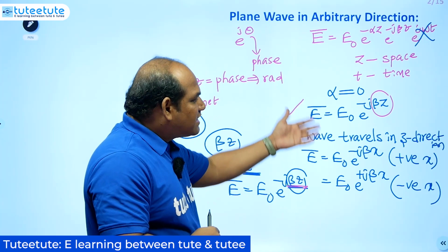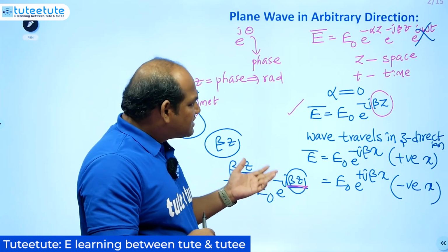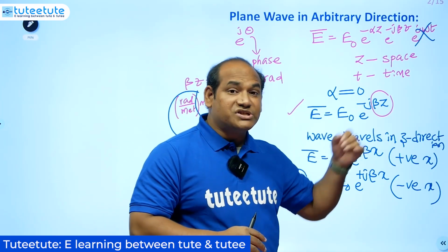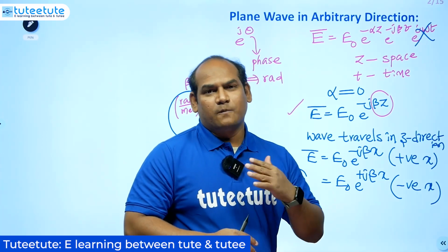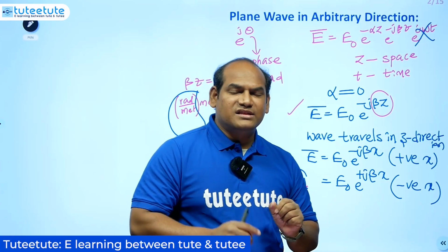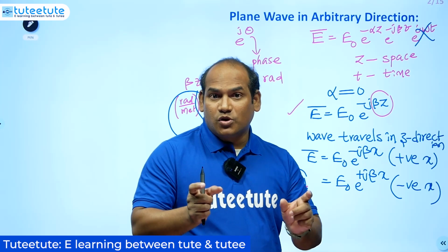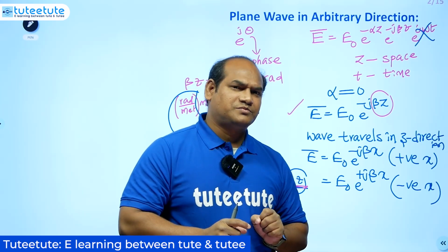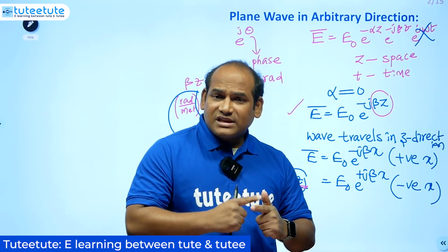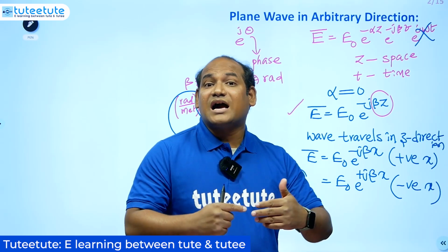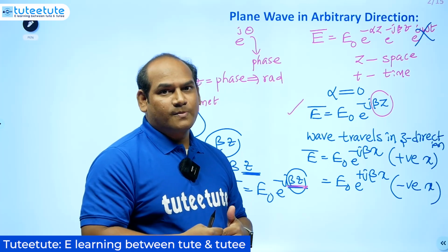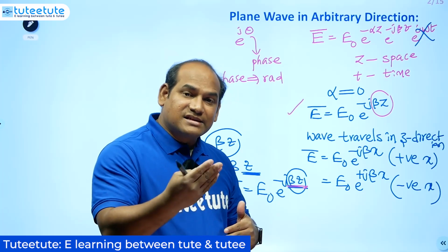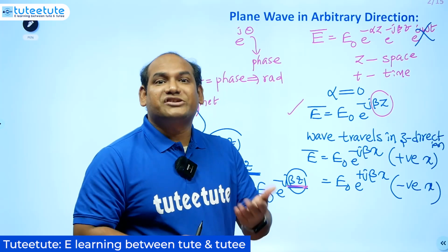But all these are standard representations, and we are saying clearly that the wave is traveling in the positive z direction. But the concept in this particular video is about the propagation of the plane wave in arbitrary direction. That means when the wave is traveling not just along the x direction, but along the x direction and along the y direction also.